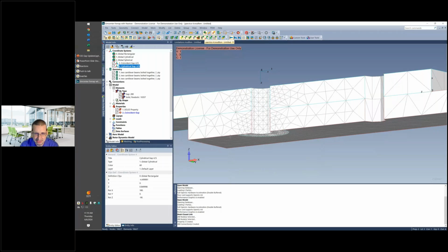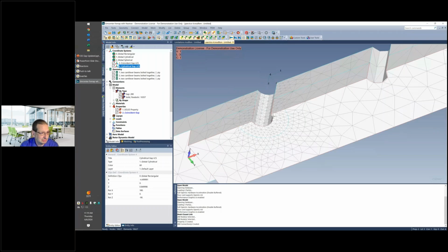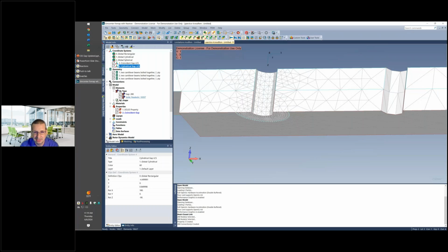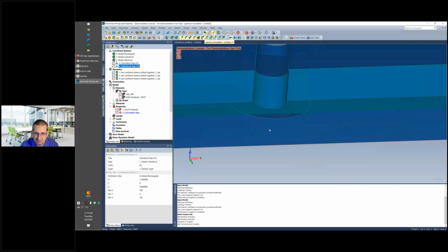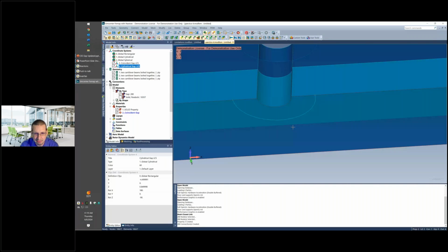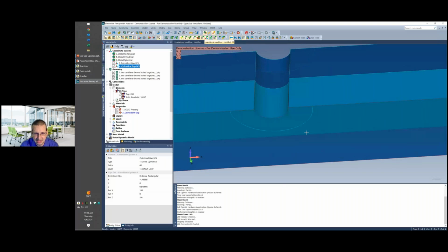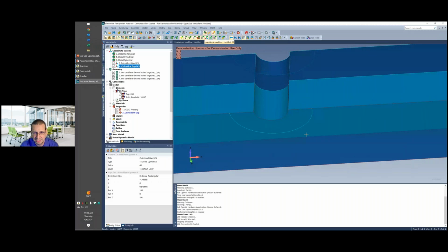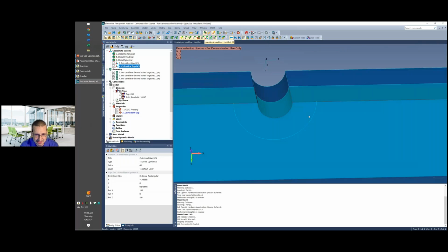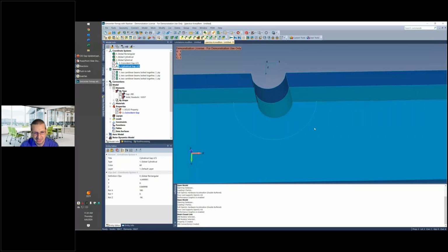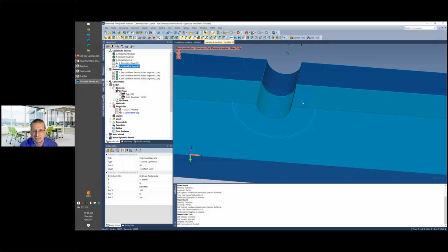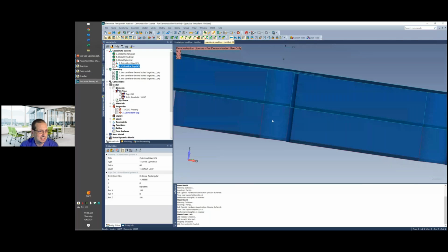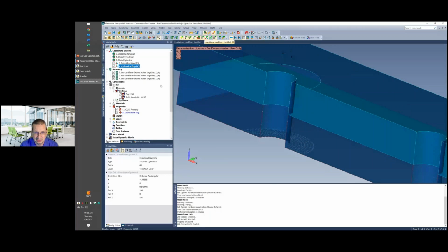At this point, one of the things I really like to do, just to double check, is verify that I do actually have a coincident mesh. I like to turn off the elements and then just do a little rotate or motion of the model. You'll see that the icons for the gap elements disappear. And what we should be left with is any sort of physical length to the gap elements. Now, because this is coincident, there shouldn't be any physical length. So this rotation here just confirms to me that I do actually have coincident nodes. So it's just a double check because it's so easy to make that mistake or make an assumption and forget what you're doing.